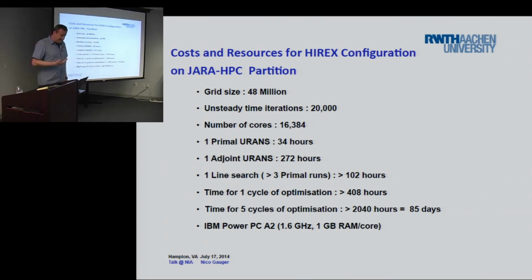Because right now, if I go to Mehdi and tell him he's got to spend 8 times an analysis, it's going to be game over. Yeah, you're right. But the good news is, okay, it's a factor 8, but you are mesh level independent. You could go with this methodology on much coarser meshes. It's still robustly convergent. So on a structured mesh, you have from one mesh level to another global refinement already in factor 8. So the truth is really it's not so less efficient than other methodologies.